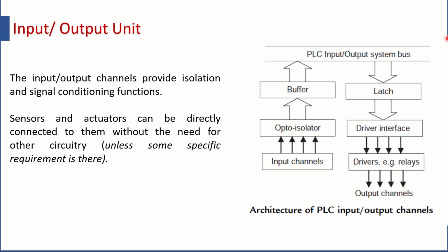So the microprocessor can maximum, I think, source up to 10 milliampere. Now you cannot afford to run any motor, any LED, any hooter, any pilot lamp with the help of this 10 milliampere current signal. Therefore the driver interface is there, and always the outputs are connected to some driver.